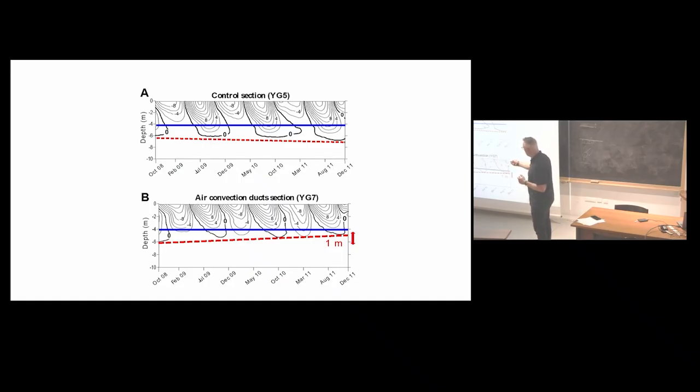That's a zero isotherm, pretty much like that. And then we just created, in just a matter of a winter, 1 meter aggradation of permafrost to control road degradation. Anyway, just a little application of natural principle and physics to road infrastructures inspired by nature.